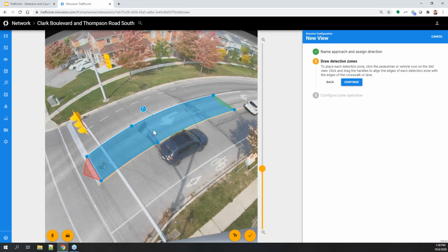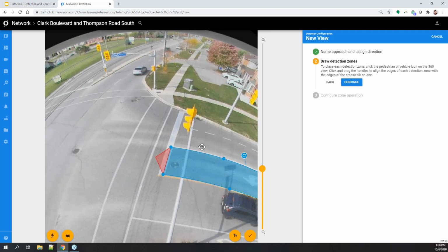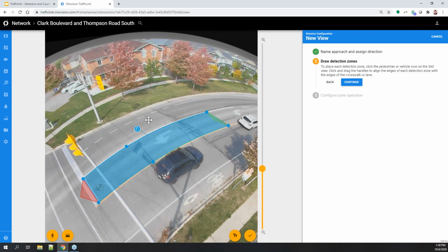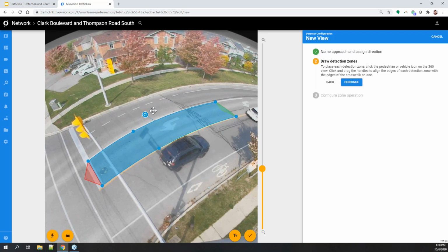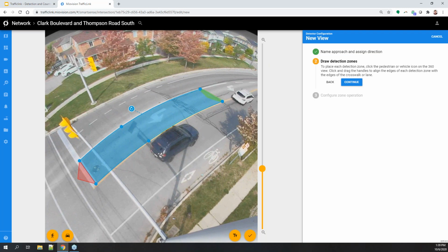You'll also notice the directionality of the zone. Enter in the green, exit from the red. The directionality is important for a lot of reasons. You don't want wrong way or the following, like the left turns from over here, coming across it and placing a call in your left turn zone, or you don't want wrong way drivers placing calls for whatever reason. But with that said, you could use this as a wrong way detector. You could flip the zone around and know when somebody is driving the wrong way on your roads here. So you could get clever about some of the applications of it, but generally you're looking for the entrance to the exit of the zone.